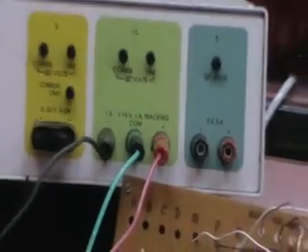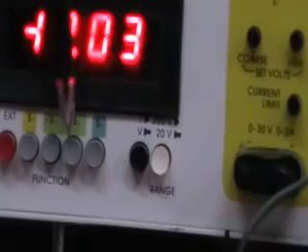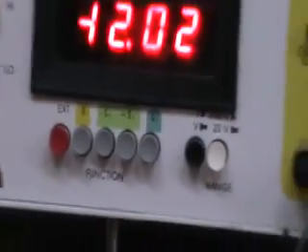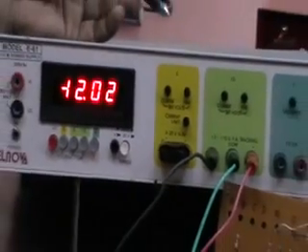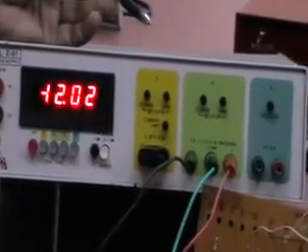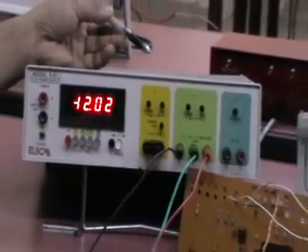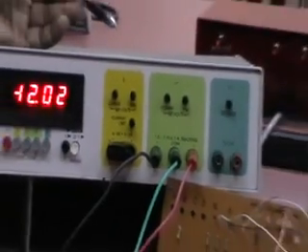You can see these variations by pressing the plus S2 and minus S2 switches there. And we can make the variations by using the coarse and fine knobs, setting plus 12 and minus 12 volts. So we will give the inputs to the differential amplifiers. Coming to the experimental part, we should apply an 8 volts peak triangular wave with a frequency of 200 Hz.